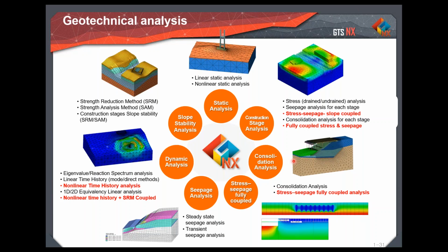And once we are done with that, if we are going for stabilization techniques like stone columns, sand compaction piles or plastic board piles, what we do is we just simulate those conditions, and using those conditions we can even find results like stress with respect to time, the settlement and the pore water pressure. So even the stabilization techniques can be applicable in GTS NX, and you can perform consolidation analysis for the same.